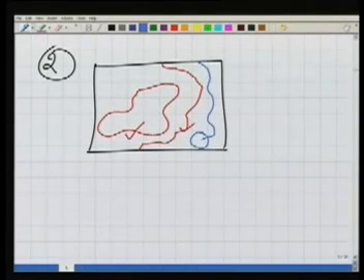It's not possible. Similarly, we cannot have a contour like this. Either it must close or it must start from a boundary and go to the boundary. Now this is very easy to understand why it is so. When we are intersecting an undulating terrain by the horizontal planes, we'll have within the boundary of the maps these characteristics.